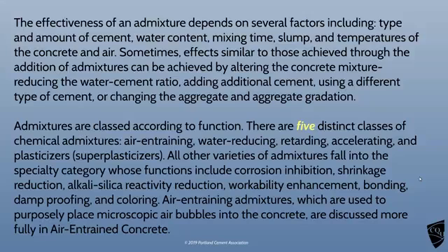The admixtures are classed depending on what the functions are. There's generally 5 distinct uses or types of an admixture. There's ones that incorporate more air, so they trap air into the mixture, makes it more lightweight. There's ones that reduce the amount of water, makes it more dense. There's ones that retard or accelerate, i.e. they slow it down or speed up the setting and the hardening. The setting and the hardening are 2 different things actually. And you've got plasticizer, which just makes it easier to work with.